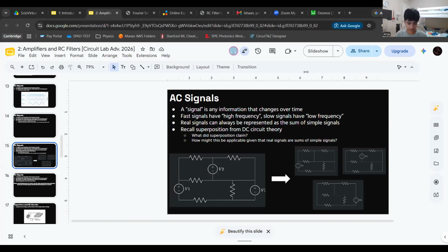So for superposition theorem, if there's a current source, then it's replaced by an open wire, right? Yeah, that's a detail of how to do the actual algebra and solve it out, but that's correct, because a current source forces a particular current, but it doesn't care about what voltage is around it. So an open wire can have any voltage between those wire nodes, but it can't have any current. But that's kind of beyond the scope of what we're talking about today. We're just thinking about voltage sources for now.